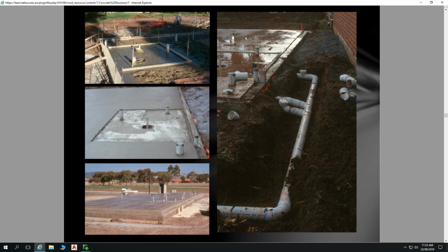And in scenarios where you're doing an elevated floor, let's say we've got plywood flooring on stumps, just a flat platform floor, in that scenario you can't do a set down. So what you have to have is overflow protection on all of your fixtures. So it's a bath with a little hole right near the top that's attached to a pipe. In case you leave the bath running and then you go out to a call or get on the internet and forget about it, that excess water is just going to go out through that overflow protection rather than onto your floor. Same thing with your laundry tub and hand basin, etc.